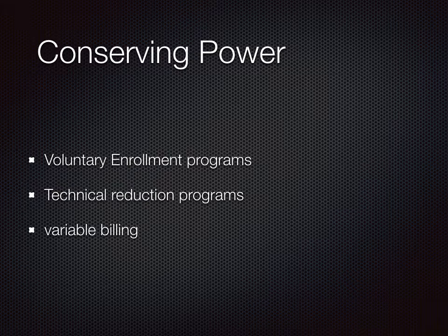In Florida, the Public Services Commission allows relatively heavy use of the water heaters being turned off in order to allow companies to recover from disturbances on the transmission system without having to expend any fuel. Also, this has the added benefit for the company that once you turn the water heater back on, the water must come up to the temperature it was before you turned it off. Usually this is within 1 hour. As a result, there is no lost profit for the company. However, as I have said previously, this is voluntary, and also it provides a discount for the customer.